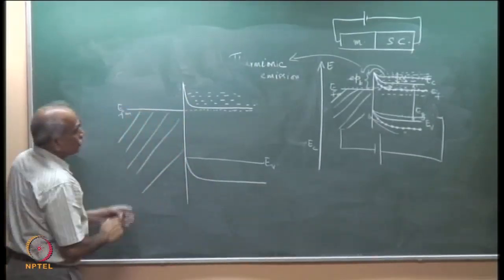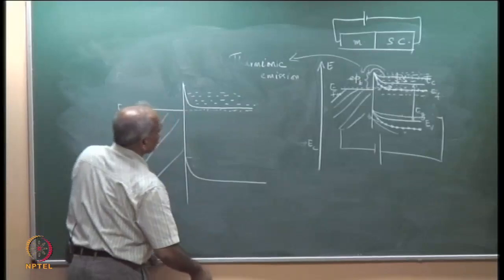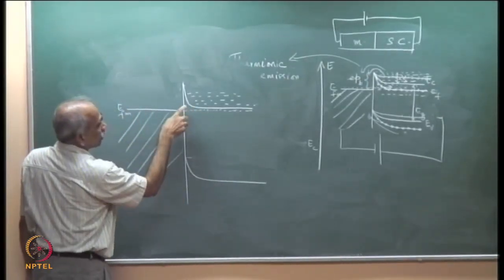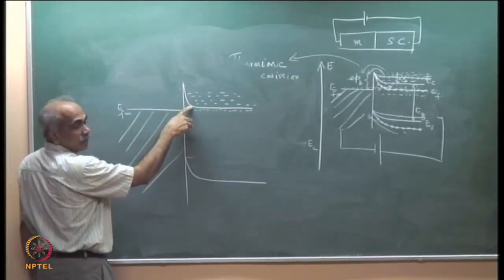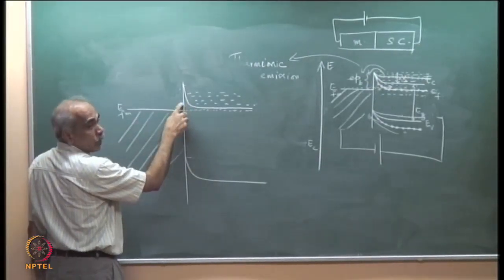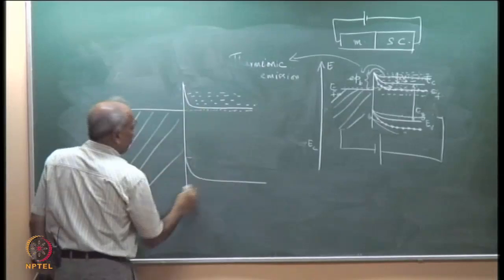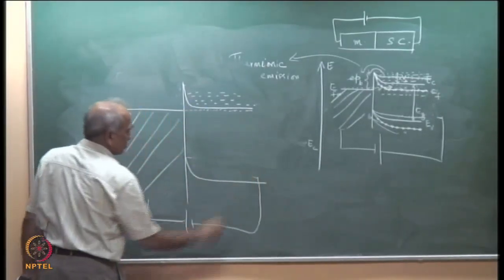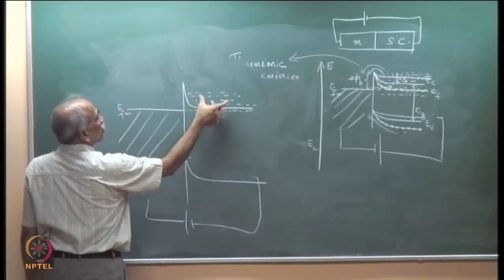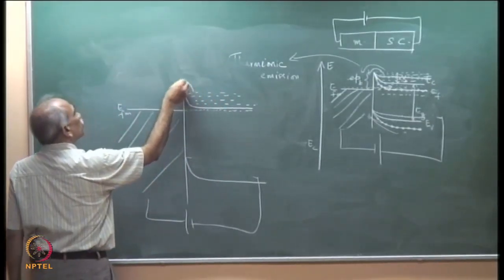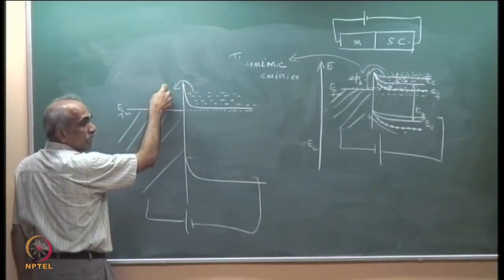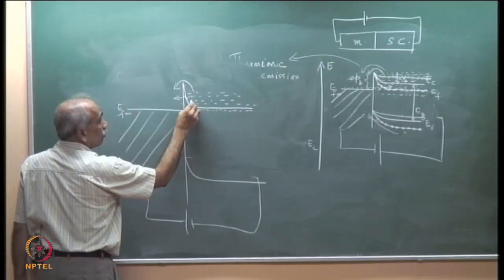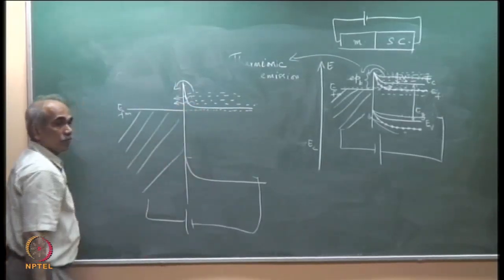So, this is the new band diagram. What I have illustrated is, now you see that in this case the barrier width is very small. Therefore, if I apply a small forward potential like this, then of course this will get lifted and electrons can subsequently jump over the barrier, but also electrons from this direction can tunnel because the barrier width is very small.